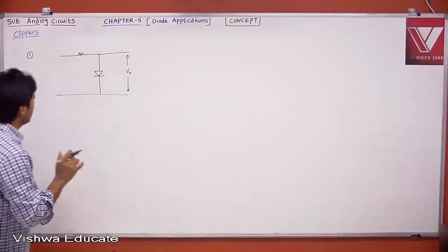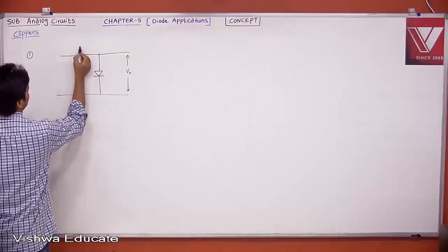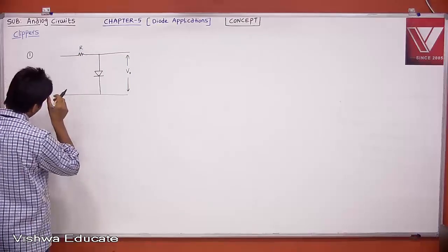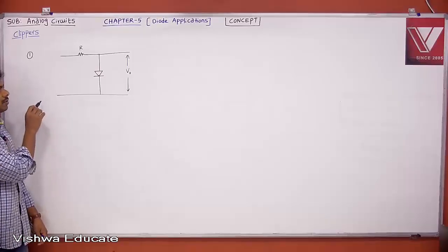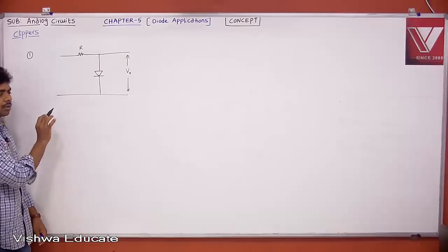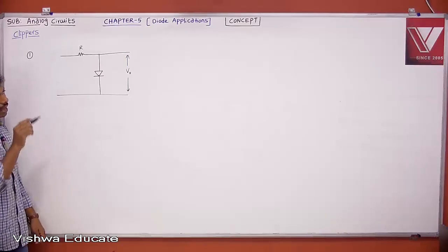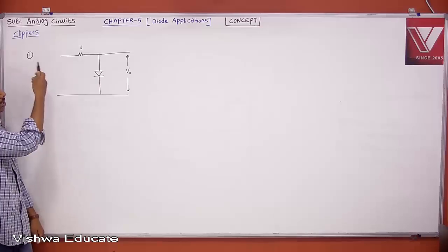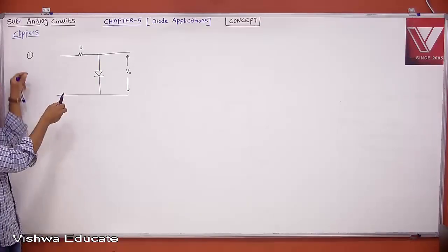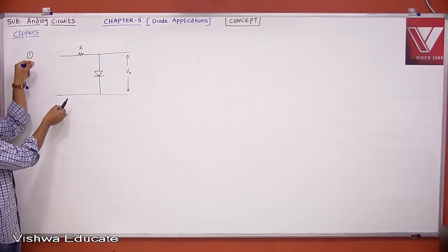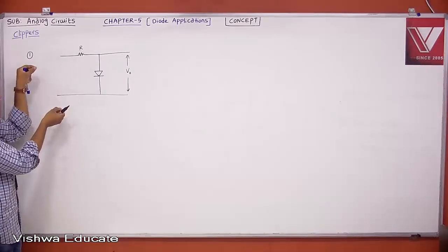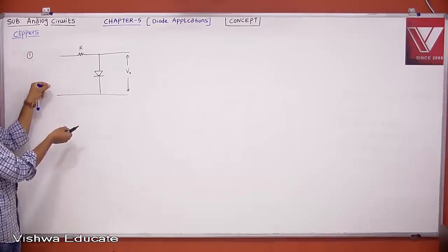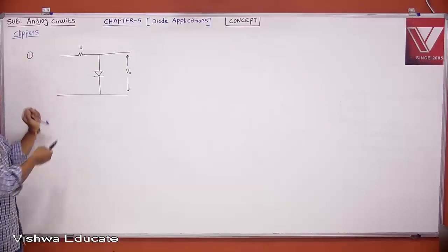Okay? Now this is your resistor, and let me tell you the procedure. Let us say input is a square wave, sine wave, trapezoidal wave, some piecewise linear, whatever it may be. In the case of a clamper, I told that whatever may be the type of the signal, just identify the positive peak and negative peak, respond for the positive peak and the negative peak, and automatically the remaining things will happen to the other voltages at the input.